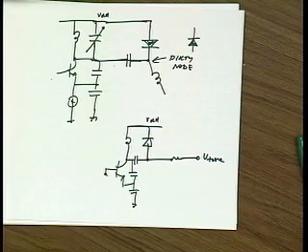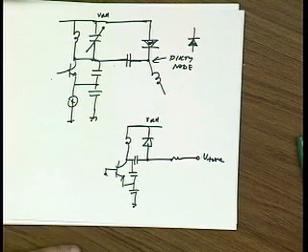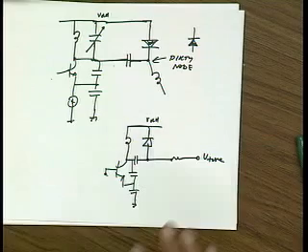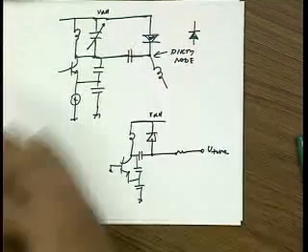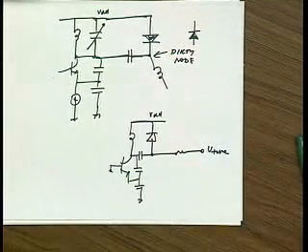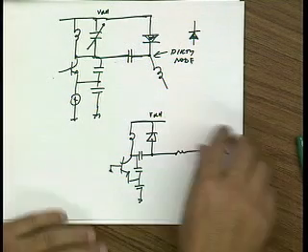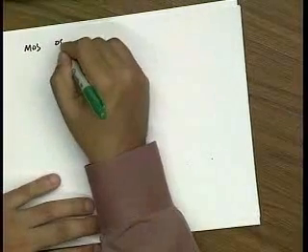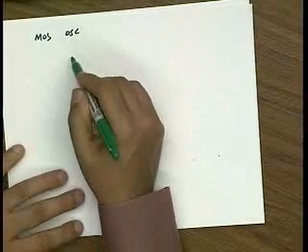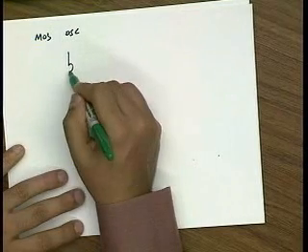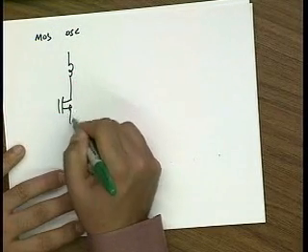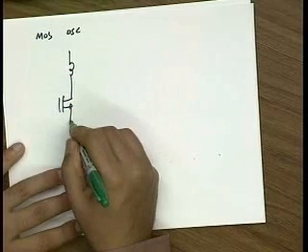Okay. Well, obviously everything we've said about bipolar oscillators also applies to MOS oscillators. So all the topologies we've discussed more or less translate directly into MOS form. Few small things change. For instance, let's take this Colpitts and build it with a MOS device.